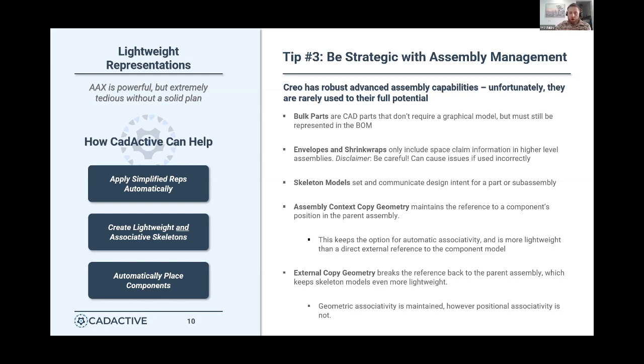Skeleton models are one of the main features that separate Creo's advanced assembly functionality from other softwares. They can be super helpful when multiple engineers are contributing to a large assembly. They allow you to share a common set of references between multiple assemblies or systems without having to load all of those components of those higher level assemblies.